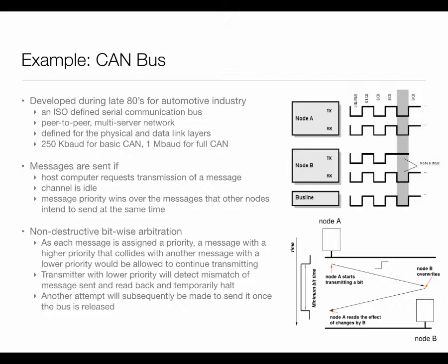The idea is that each sender is supposed to have a unique priority. So if you're sending out the bits and you're also monitoring the wire, at some stage you will encounter the first bit at which the different priorities of currently active senders mismatch. Let's say I have one guy whose priority is 1100 and the other guy whose priority is 1110. Both of them will send out one, match, no problems. So I'm hearing what I'm receiving.